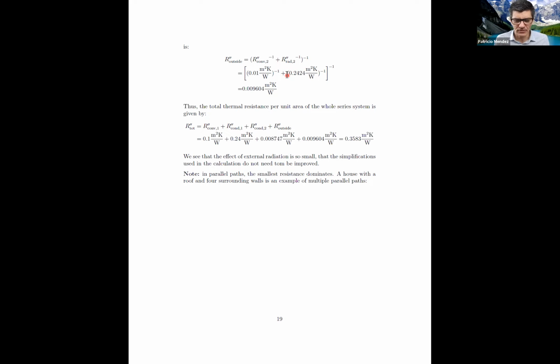When I put all this together, now this problem that is done as accurate as we could for one wall, we get this total resistance that accounts for brick, stucco, convection inside, convection outside, whether the air is stagnant or the air is forced by the wind, radiation inside and radiation outside. What else do we ever want, right? And what we see is that because many of these factors were secondary factors, the value we get is more or less the same as before.